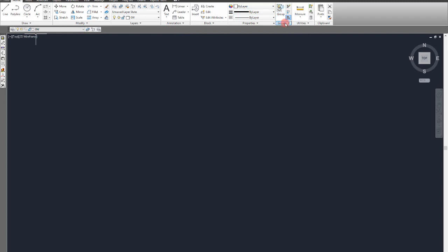And here we have another command, groups. You can group elements, but I prefer using blocks instead of groups for most of my drawings. Of course, you can group elements. For instance, you can group a table with 6 chairs around it so that when you select one thing, it selects the whole. And we have measure here and copy paste, you know about it. Copy and paste are universal commands for all drafting programs.